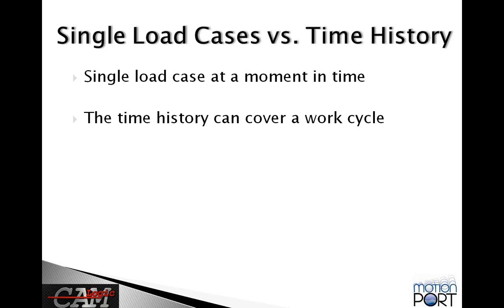And the other thing would be if you have a load case or a set of loads from analyzing a work cycle, and you want to review all the stresses throughout the work cycle just to make sure that you're identifying what are the key stress conditions of interest that might be used in durability. So there's two variations here. I would suggest for best practices that when you have a system that goes through some kind of duty cycle or work cycle, it probably is a good idea to look at more than one load case. And you can do that by doing a sequence of these single load cases.